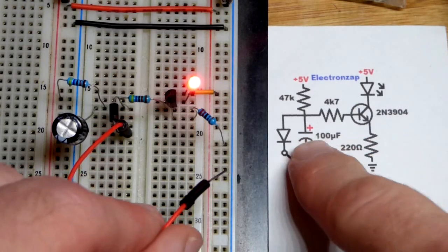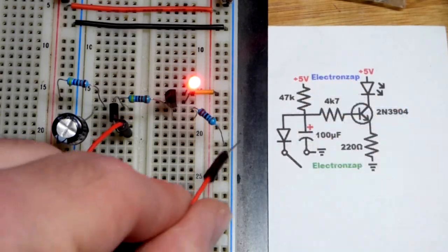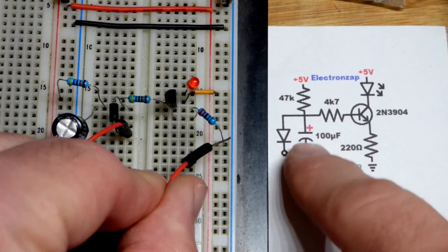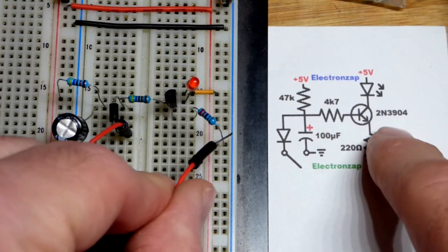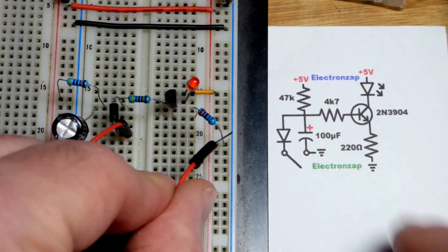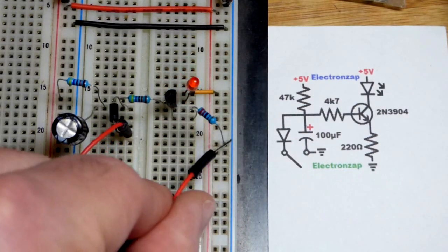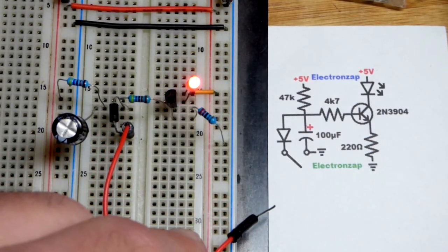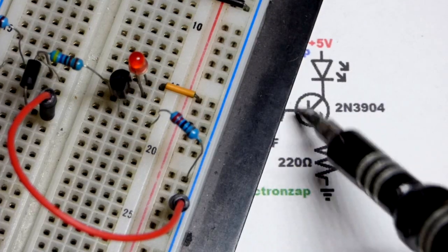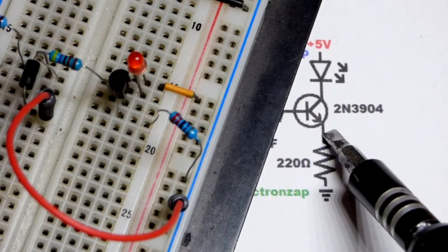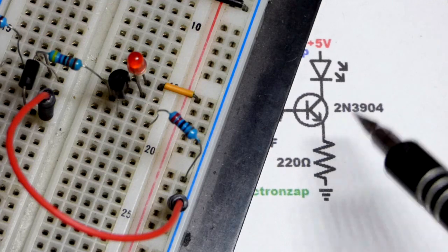For this video, I combined a capacitor whose voltage goes up while it is charging with an NPN bipolar junction transistor wired as a current source. That way we can fade on an LED while it is turning on. The voltage at the base goes over to the emitter, but you lose about 0.6 volts. We'll come back to that later.